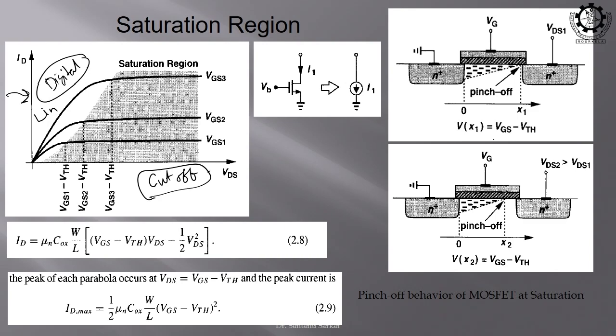Okay. So, we have covered the calculation of current expressions, how to calculate the current expression considering the unit chunk of electrons moving because of the drain potential, and how to calculate the I depending on QD into velocity. Then we calculated the current, and for different regions of operation we have considered how it will behave, and we also saw that if our VDS is greater than the overdrive voltage, pinch off will occur.